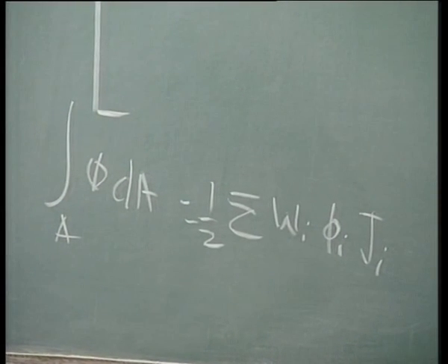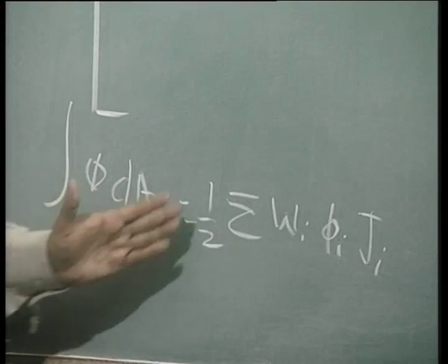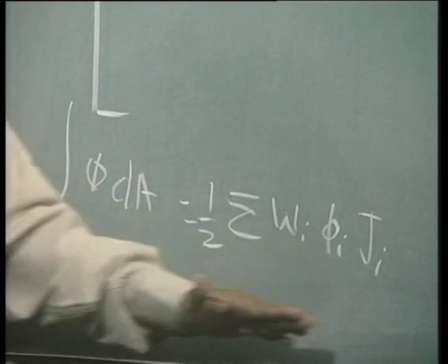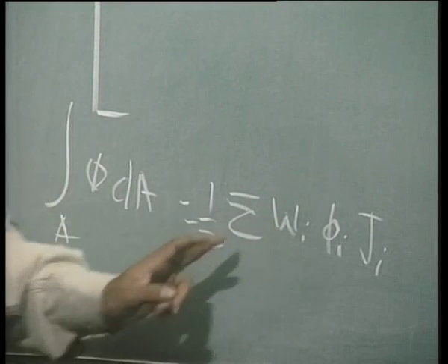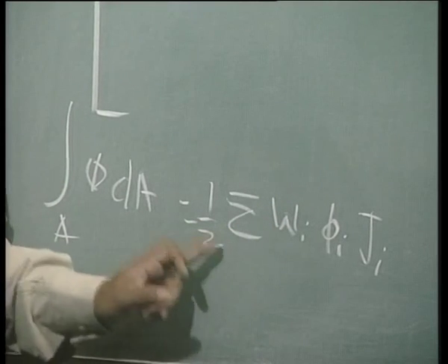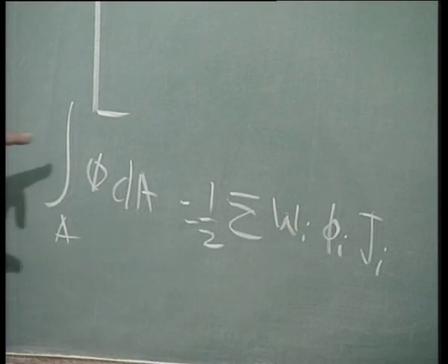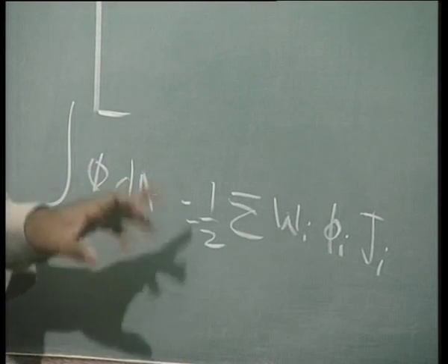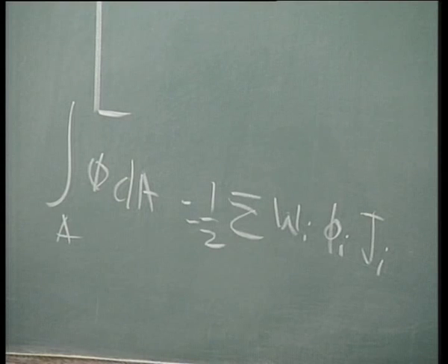That is because of the area calculation in the natural coordinates, but nevertheless this is how many textbooks write. If this half is not there, then it should be in the weights. So you calculate whatever is there in this phi, like what we did for the quadrilateral element, in the same fashion, and get the stiffnesses.